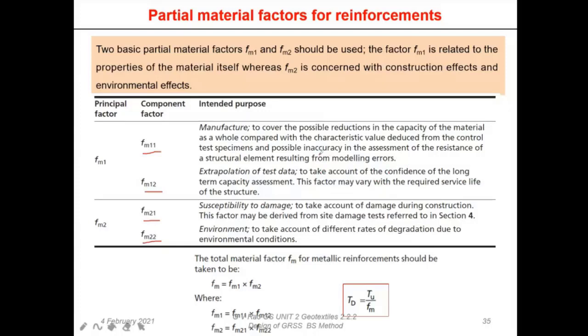You remember we have mentioned we are going to do the index testing for weight, width, and tensile strength, isn't it? And obviously that value is going to be used for the entire design. Basically, that means we are going to use such long and wide materials, and we are still basing it only on a 200 millimeter wide sample. So there is a modeling error when you are extending this strength to wider samples in the field. Naturally, that is going to be there.